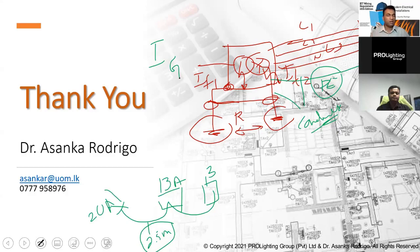But keep in mind, when your earth electrode system is connected to a lightning arrestor system or your external lightning protection system, when there is a discharge, that discharge current can go to ground and the ground potential rise can increase. Because of that, you have to minimize the resistance of the earthing system. In that case, sometimes, in order to measure the total electrode system, even with the structural earthing, you can put a few inspection points where you can connect the earthing measurement equipment and measure it.